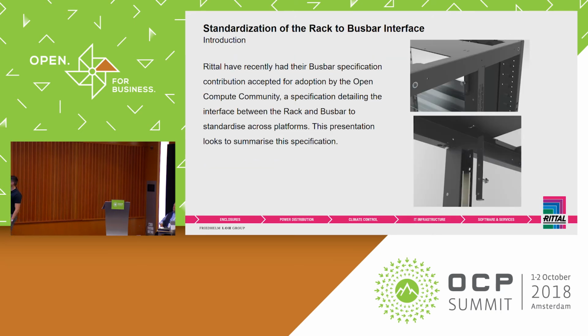So this actually is floating. The way it is used is you bolt this with this plunger here onto the side of the bus bar, and then you can't really see it, but there's this hole here in the top of the frame. That is how you're supposed to line this sheet metal part up with this hole at the top of the frame, and that will drive the correct dimension of the bus bar.